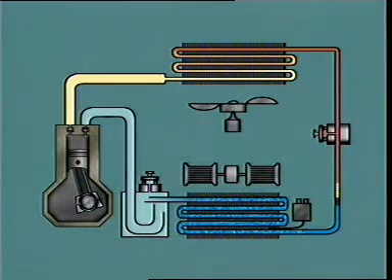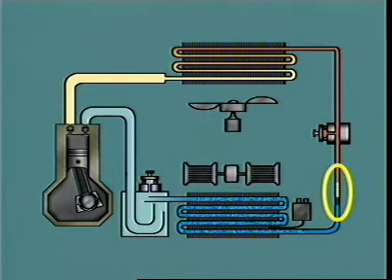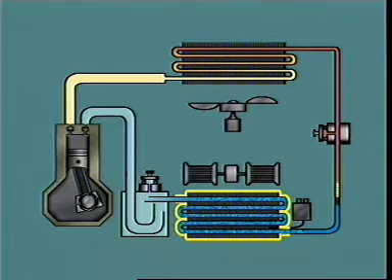The reduction in temperature causes the refrigerant vapor to condense and turn into a liquid, which flows to the filter and then to the orifice tube. The liquid refrigerant loses pressure by flowing through the fine tube and is then forced to expand suddenly by passing through the nozzle and entering the larger volume of the evaporator.